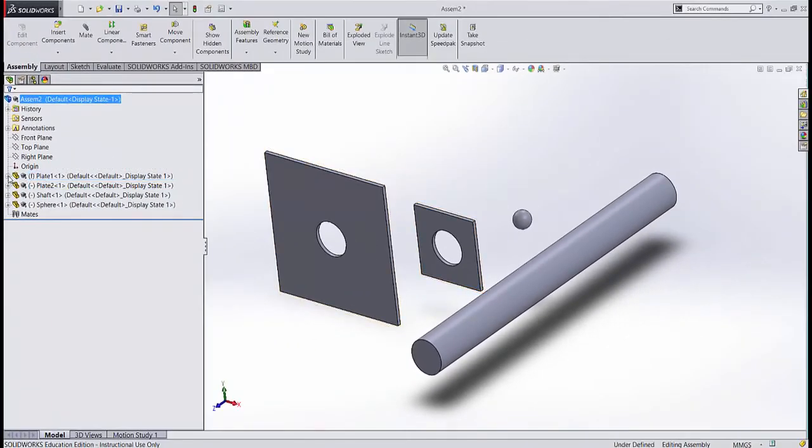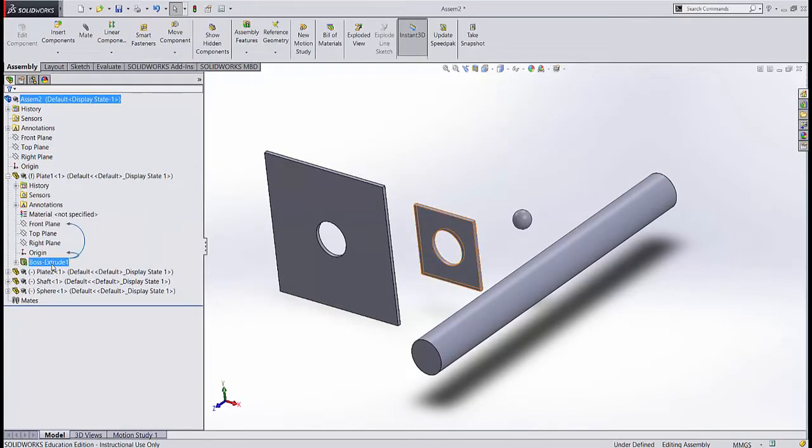If you make changes to any of your parts while you're in the assembly, these changes may or may not propagate back to the original part depending on your settings. So I urge caution, and generally for novice users, I recommend that you do not change any of the features of your parts within an assembly. If you wish to change features such as length or depth of extrusion of any of the parts, you should go back to the part file, upon which when returning, the assembly file will update to reflect the changes that you made to the original part.